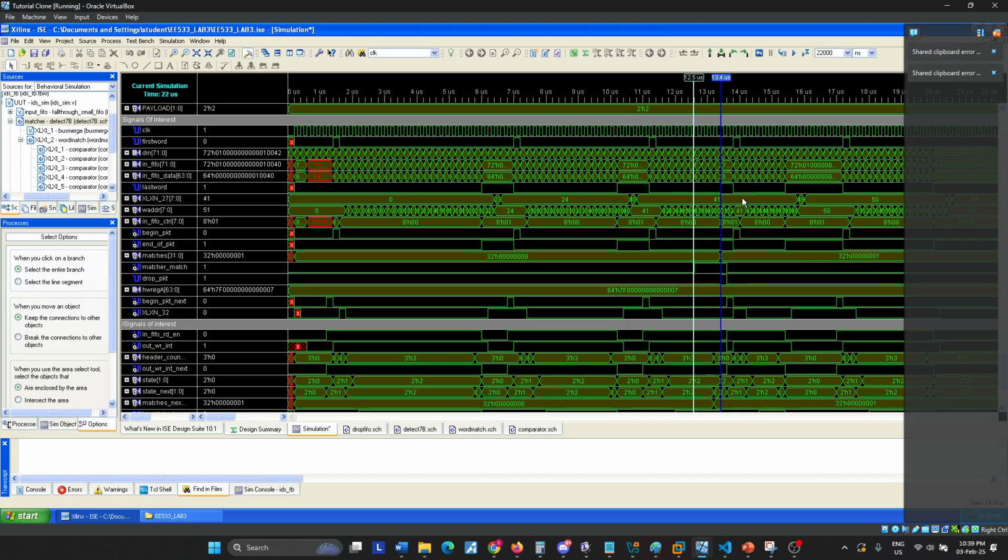So essentially, this indicates that 10 of my packets were dropped from 42 to 52. All these 10 packets will be dropped because my write pointer has essentially moved from 52 to 41 again. And this is how my 7-byte pattern matching along with the drop FIFO would work.